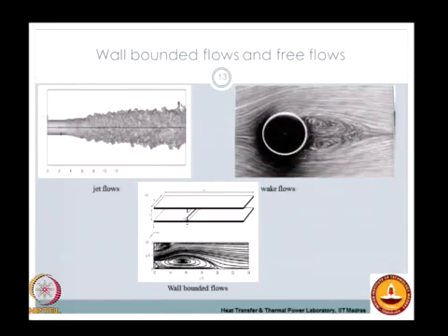So if you look at the boundary layer growing downstream of this particular object, you are talking about external wall bounded flow. And far away downstream, this is called the wake region here, where the boundary layer theory cannot be applied and the flow separates, and then again you have variation in the velocity profiles in the wake region. So these are called the wake flows.